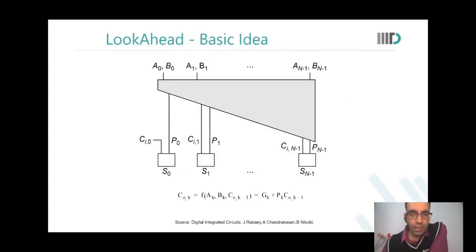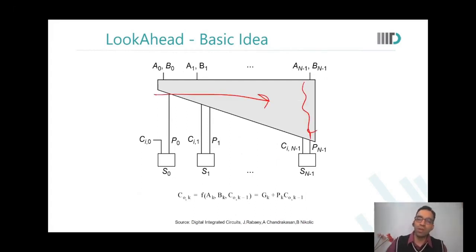Thank you. Yeah. So after the carry select adders, you must have heard about what are called carry lookahead adders also. So what do carry lookahead adders do? They do something similar to this select thing, and they say that as you go into the higher bit, there will be more time, and therefore you could have a longer path set in there.